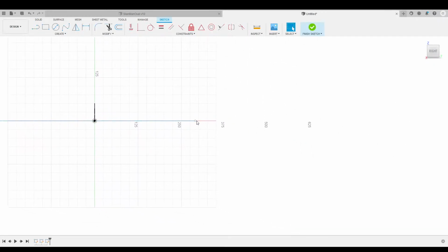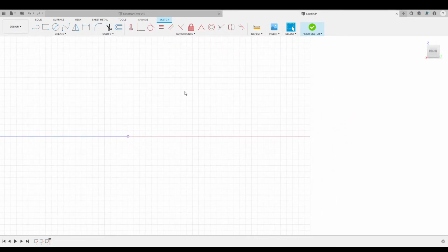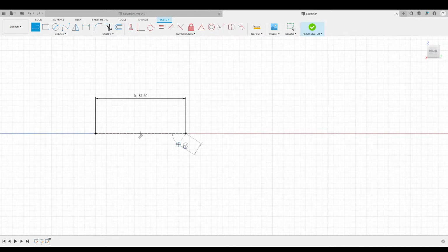But because this is a new sketch, it presented us with the dot, but we're going to go ahead and project that dot into our space, just as a good habit here. So we projected it. We're going to do our line, construction line. It's still the same, track width. It's parallel, it's flat. Black line's good. Go in here. Track width. Go up here. It's unconstrained. That's fine. We're going to do our dimension.